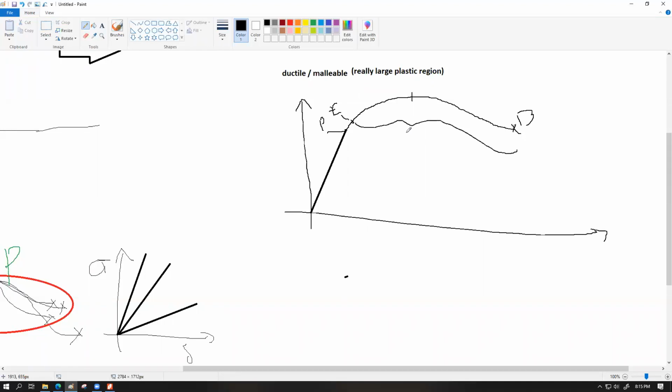Ductility is applicable for the type of deformation where a metal is stretched into smaller dimensions, for example, making a wire. Let's say you have a cylindrical piece. If you apply uniform force on both sides, you can make it into thinner wires by pulling, under tensile stress. If we do the plastic deformation by tensile stress, we call that behavior ductility, or the material is called ductile.